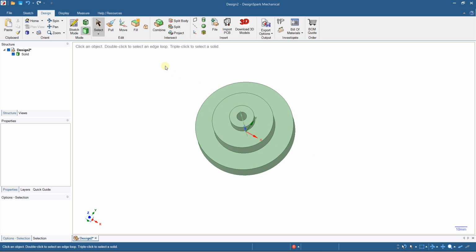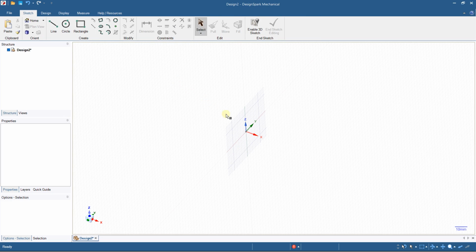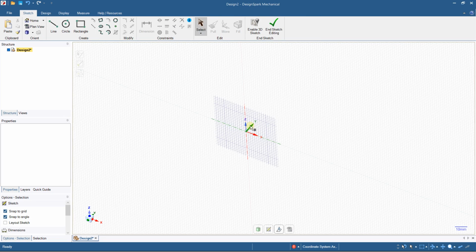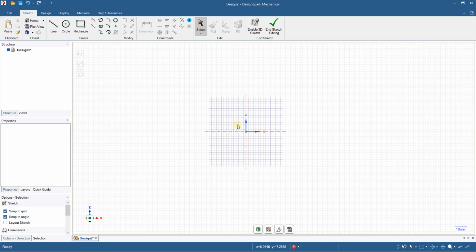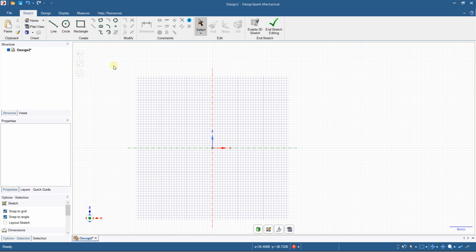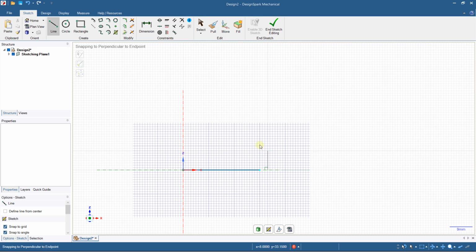You can also use this if you want to create any complex models, like a vase, something like this. Create a sketch again, and let's select the Y work plane. I can activate my front view. And if I want to create a vase, I can create a line. My first line will be here. Let's activate 30 mm. Press Escape, and then click on my spline tools.